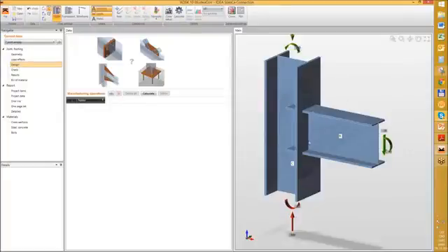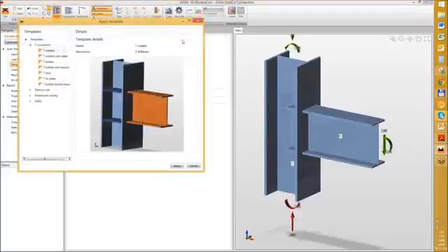Any connection which you design, you can save as a template, and again you can use it as a template, apply template. We recognize the shape of the connection, and the program offers a number of possible solutions of these connections. Like here it is a welded connection, this is welded with end plate, this is bolted connection with end plate, this is connection with hinge, this is this stub where the bolted end plates are removed from the connection.